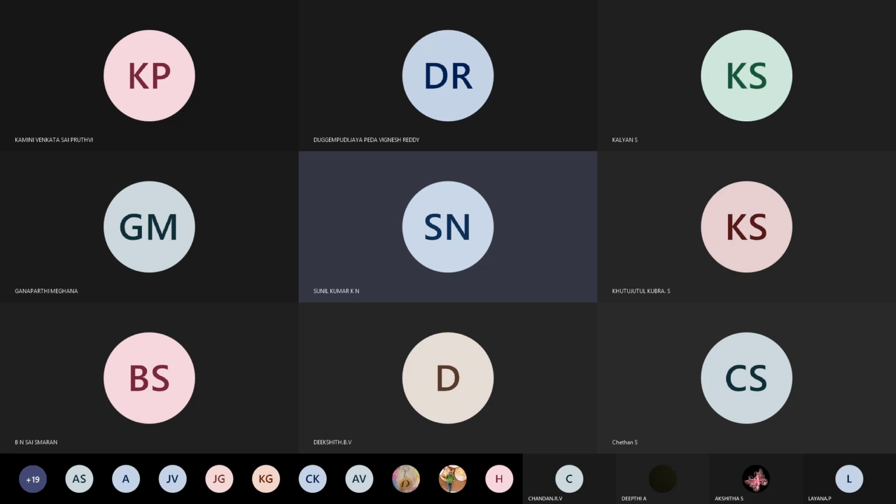So you're going to add a small signal VGS. Small signal VGS is nothing but this is the small signal VGS. So that means you're going to vary. You're going to consider the small signal, which is a time varying signal, which is going to vary this operating Q point, so that it is going to move the Q point to shift above as well as below like this. So that is the time varying signal for which you are going to get instantaneous gate to source voltage to lie within these two.